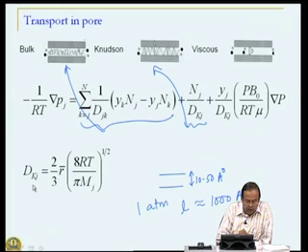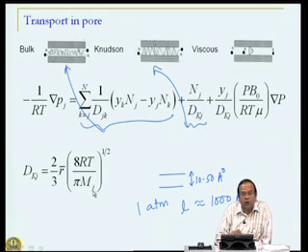Notice here we represent Knudsen diffusion as D_kj, k for Knudsen and j for the species, and it is tied down to the property of the species, M_j. But notice here that it does not involve another gaseous molecule. So, whether it is a multi component system or a binary system, or whatever may be the system, the diffusion is independent of what else is there. That is a characteristic of Knudsen diffusion.